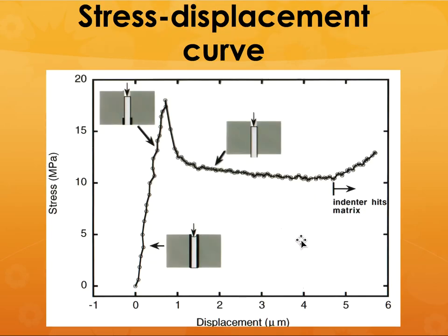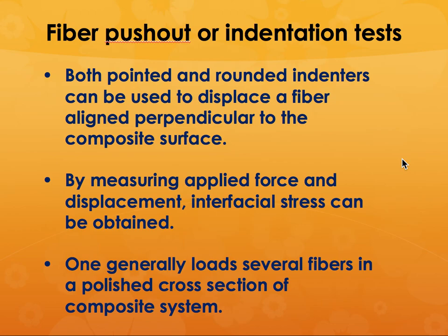This is the 3-part region for the push-out test. You plot the stress versus displacement, and your test is only valid till here. This one is probably not valid anymore, but you really cannot stop the test at exactly that point, so you let it continue, but you know that this region has to be avoided at all costs.